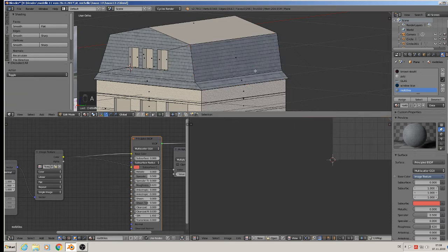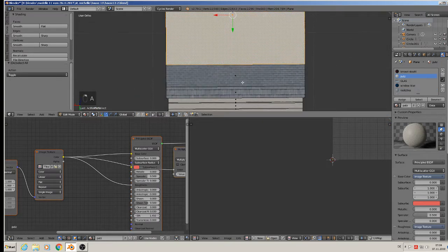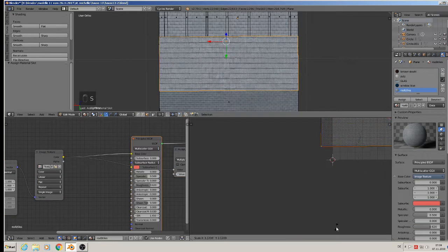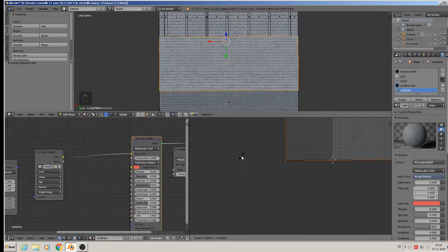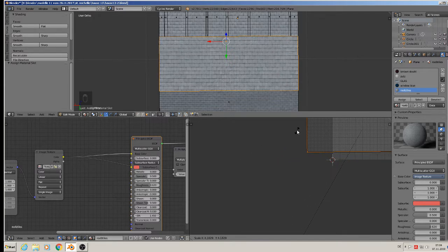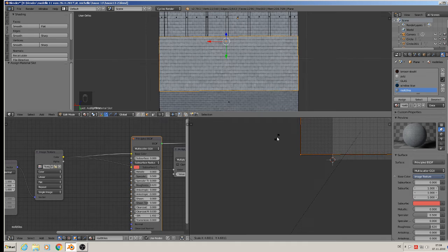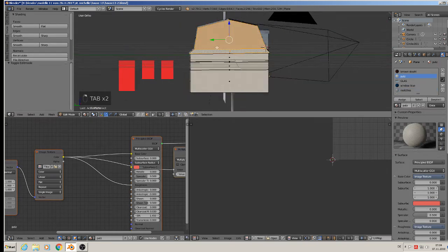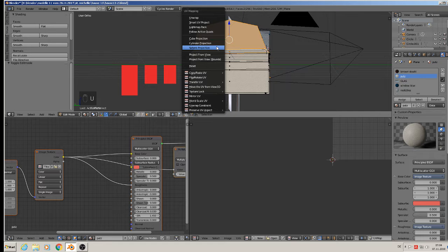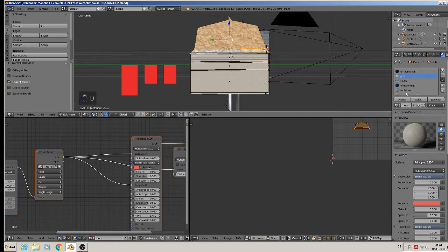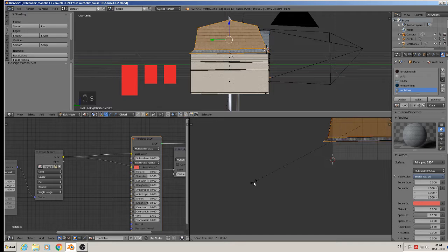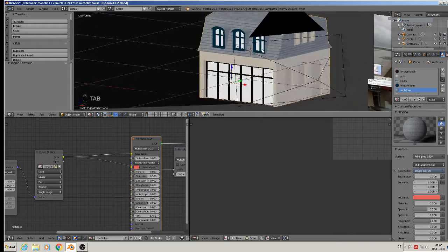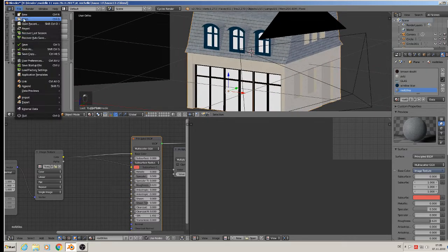I think that can work. And this one a little bit show up, and from view, roof tiles assign, scale down. That's too much. So then the last side is this side here. View, from view, roof tiles assign and scale down. Yeah, good. We have done that. File, save.